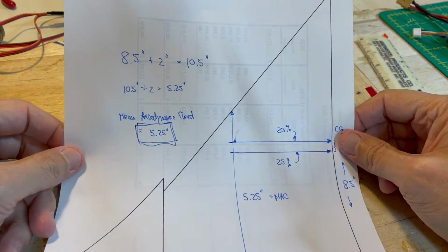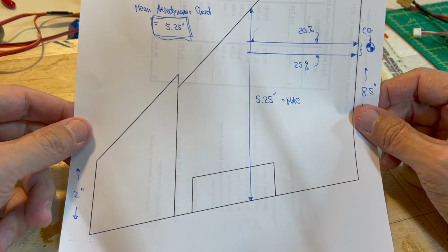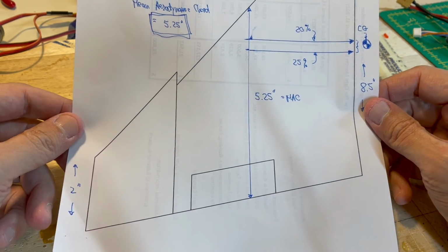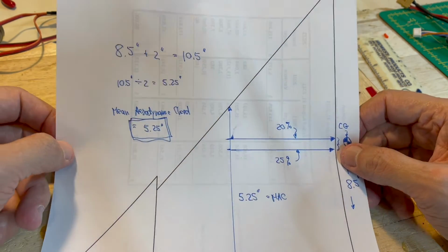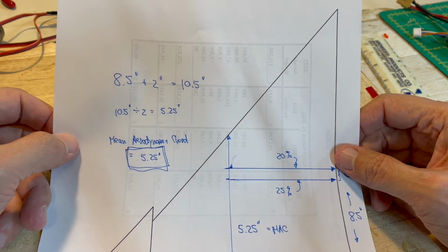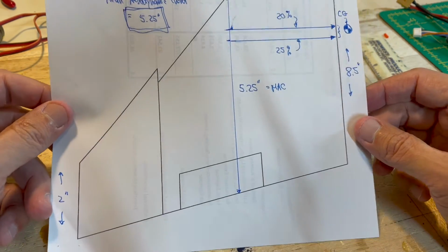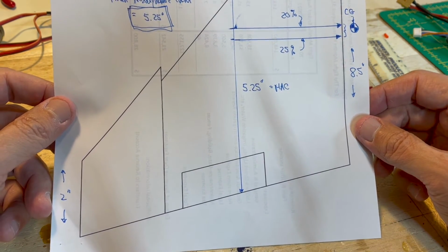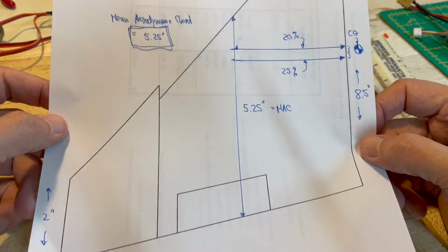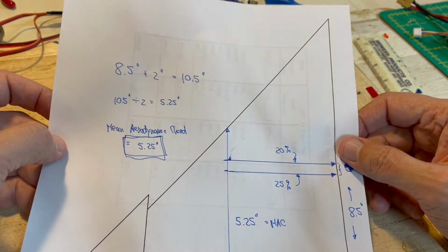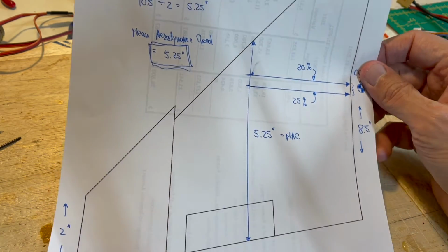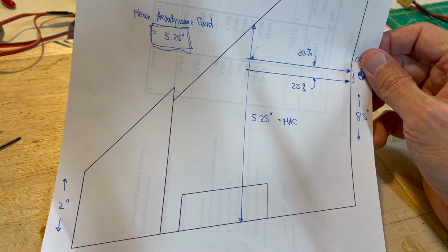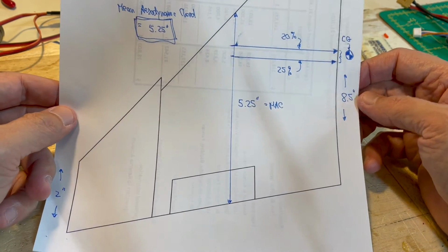So what I'd like to do now is discuss how to find the center of gravity for a swept wing airplane. This is not full size, but a scaled drawing of the wing of an F4 that I'm in the process of designing. If it does fly successfully, I'll put the links in the description. Again, for the center of gravity, you don't care about the wingspan or the sweep. It's all dependent on the chord of the wing.